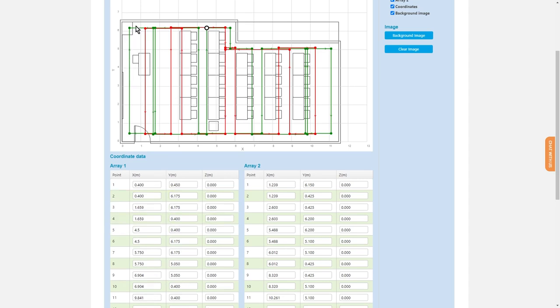Finally, on the top left here, I'm hitting another obstruction, this pillar in the corner. Now, I could move this entire wire in, or I could have added a bigger gap when I was setting up the original automated design. I would always recommend getting the automated design as close as possible to what you want as you can.